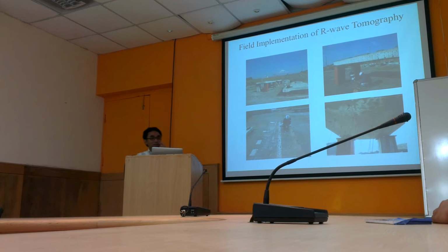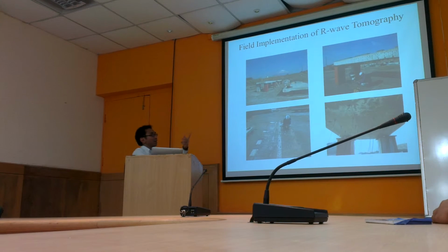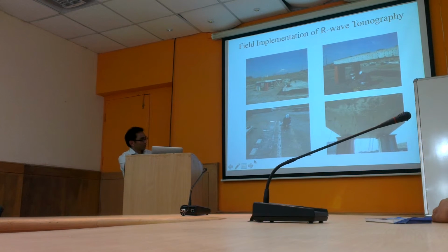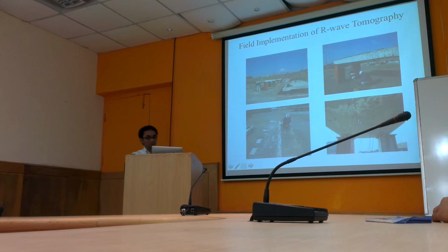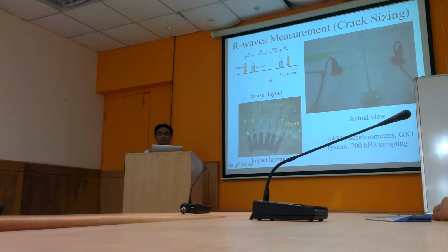And before I went back to Malaysia, we had some projects also. These are bridge decks which have been retired from service. They cut them and transported them to a certain research center. And they asked us to go there and do some fundamental testing for collection of data. So we did the same thing. We also did the measurement on top of the asphalt pavement, and also at the bottom. This is the size of the steel ball hammers that we have, from 5 mm to 35 mm. This will give different generation of frequency.